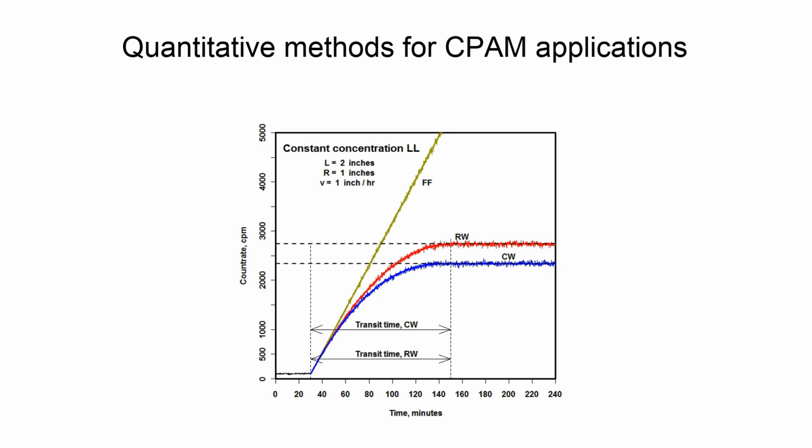The integrated counts are easily obtained simply by accumulating the pulses in a scaler or, in more modern implementations, in software. Estimating the rate of change, the time derivative, of the count rate is difficult to do with any reasonable precision, but modern digital signal processing methods can be used to good effect.